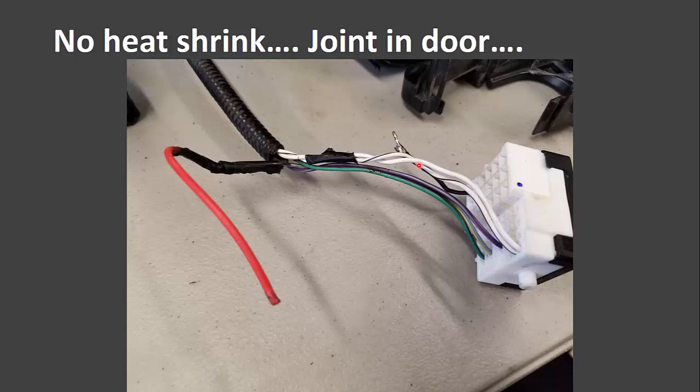They electrical taped it. You would be better off, if it was a ground wire, you couldn't do this to a power wire, leaving a wire bare than putting electrical tape on it, because electrical tape allows moisture in and it just stores underneath there and rots away the connection.